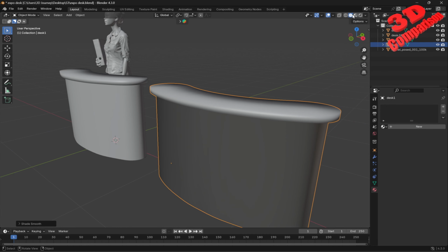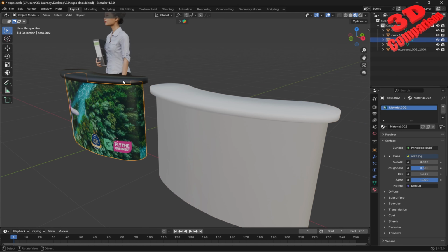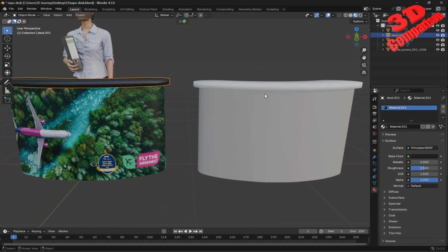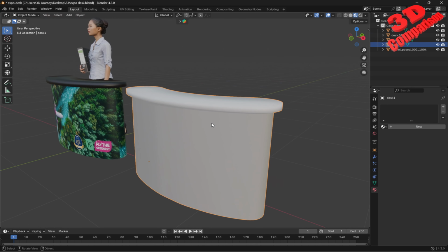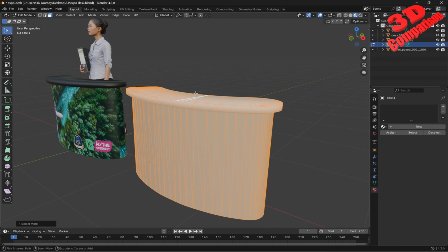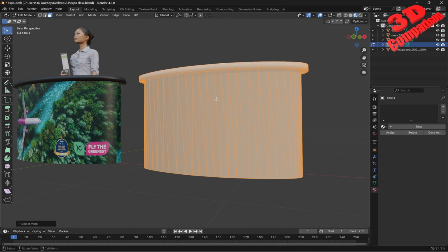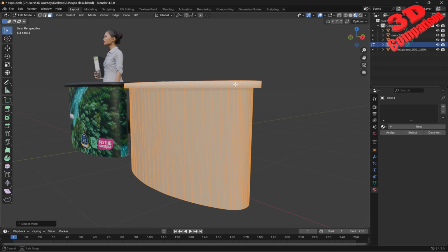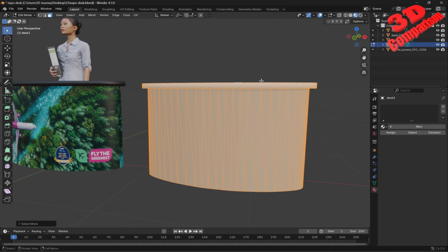Afterwards, if you want to add separate materials for the top part and the bottom part, we can easily do that. I will press tab, select the middle face over here, and I will have this expanded. As we can see, since within Solid we had that merge between the initial surface over here on the bottom and the extrude on the top, those will also be selected over here.